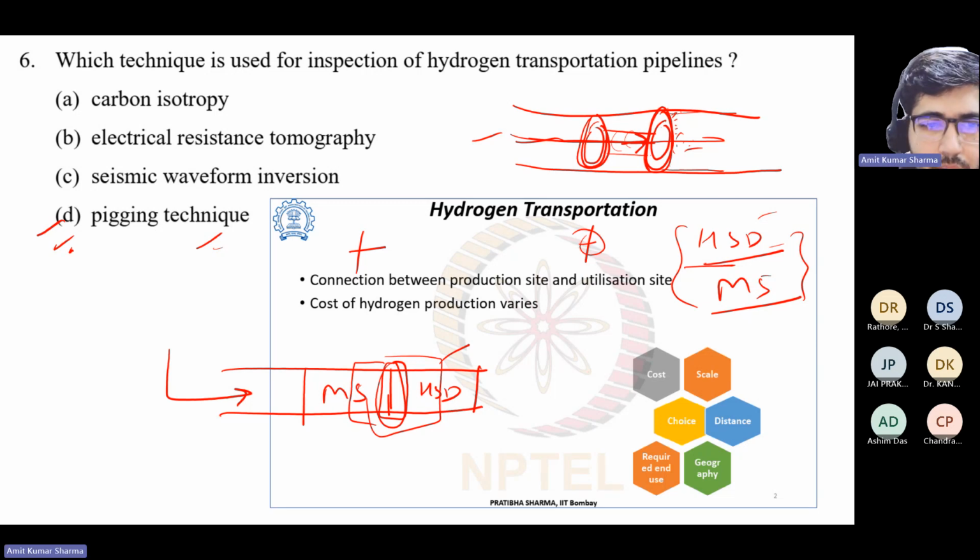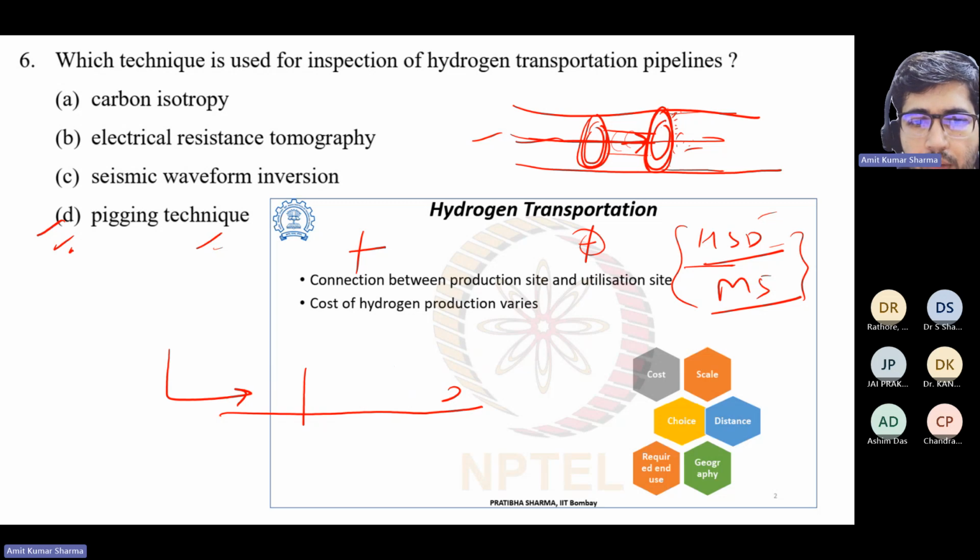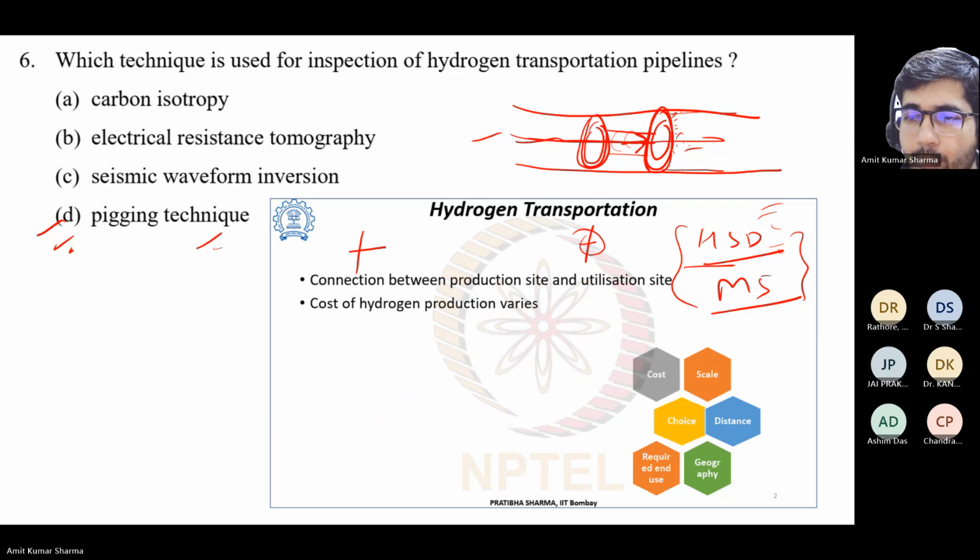So this is called the interface, where we have the mix of the two, because with the speed and the length of the pipe, they will mix together. The mixture of diesel and petrol will be of no use. So that is not the way. The way every industry follows is that whenever you want to send diesel and petrol, in between you will have kerosene, because kerosene you can add to both and it will not change the properties so much.